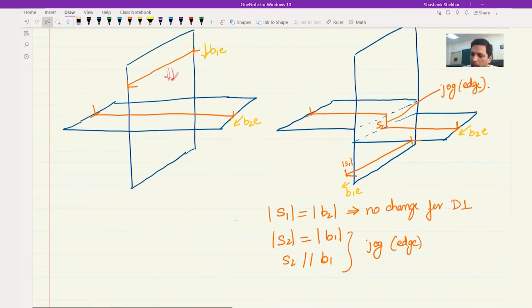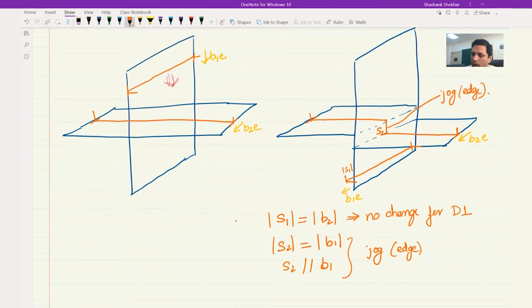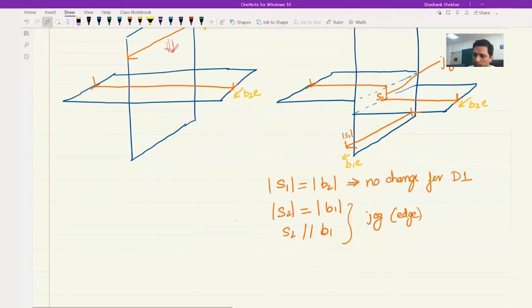Now, if you look at this dislocation, it would want to move in this direction, and this is the glide plane. And for this dislocation, this is the glide plane. So overall, when this dislocation wants to move, it can easily move along with the step size, step S2. Similarly, for S1, there is nothing, so we need not worry about it. So in this case, we can say that the step that is formed on dislocation 2 aids in glide.